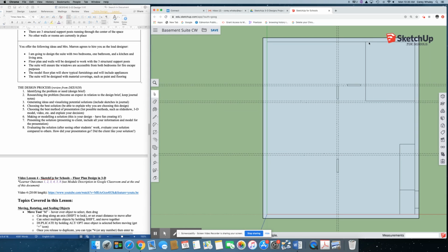So what I am going to do is also expand these walls for the utility room just so that we have that in place, and then also add that door. To expand that, I'm going to select that rectangle that we've already drawn and then go back over here to the offset tool. Okay, and we can either decide the walls can go towards the inside or outside. I think I'm fine with going towards the outside, and I want to make those exactly 4 inches. So I'm going to type in 4 inches, hit enter, and there we go.